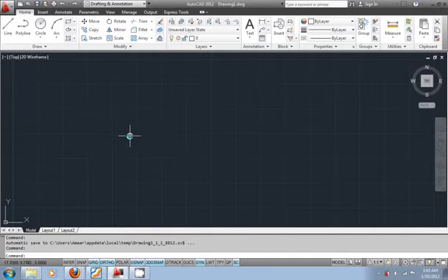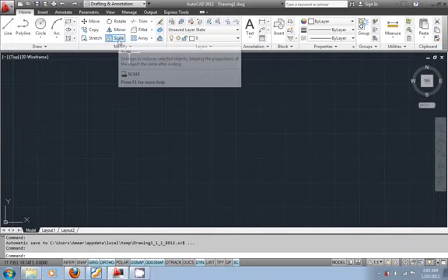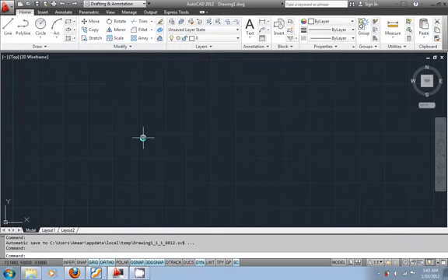Again, it's not possible in pen and paper, so that's where the advantage of AutoCAD kicks in. So you can copy any object and create a copy of it. You can mirror any object about any line or any other object so that it creates a mirror copy of that thing across that mirror line. Okay, you can always scale it to any size, small or large, whatever you want.